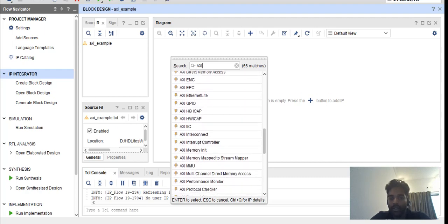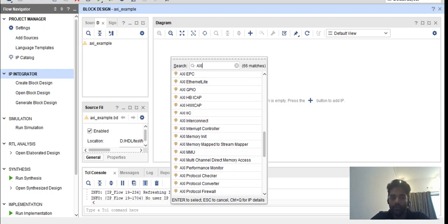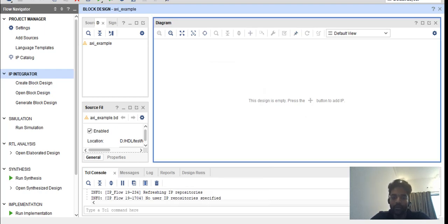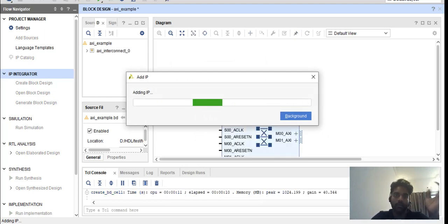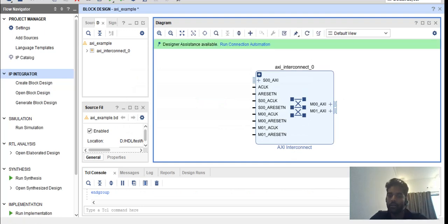so we'll have the AXI interconnect when you have the multiple master and multiple slaves. I mean more than one master, more than one slaves. You have this interconnect, and you can connect many masters. In the block design, you can have your block also. You can have your RTL also can be connected directly here.